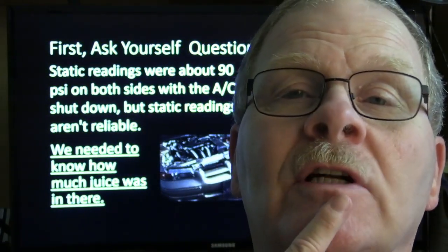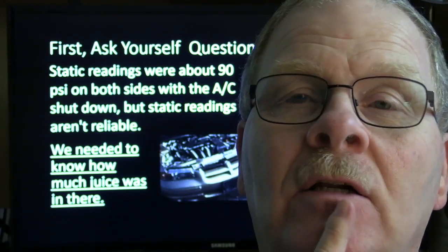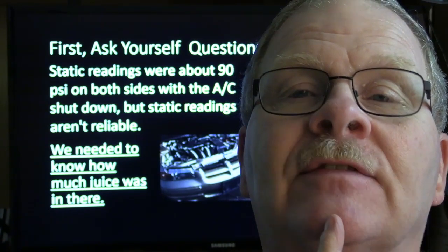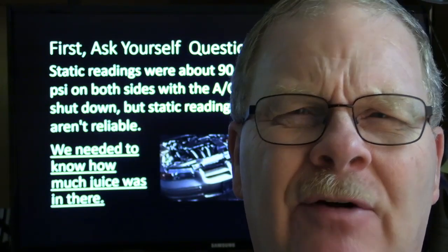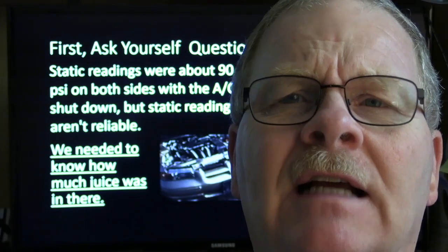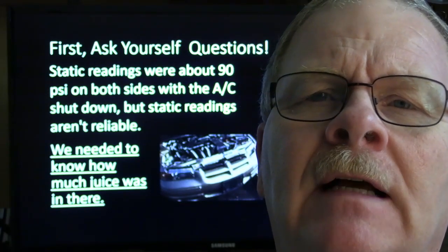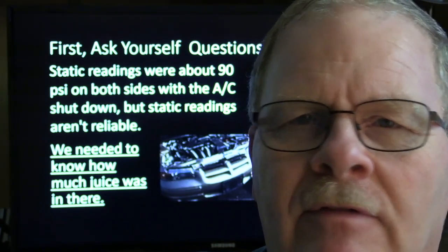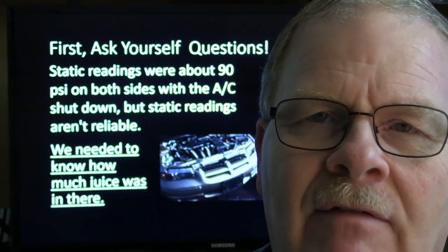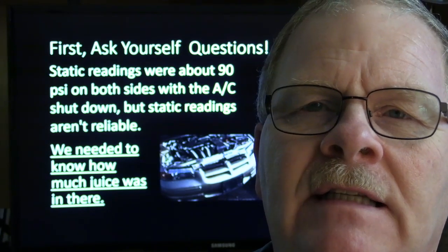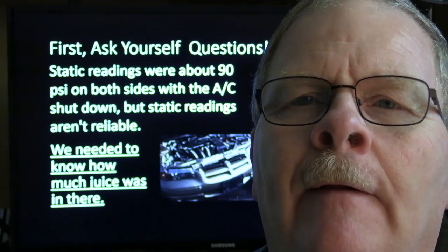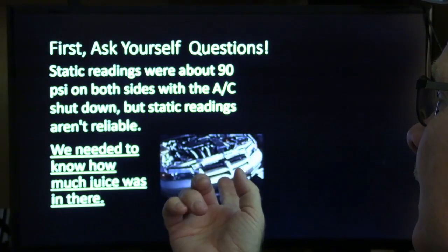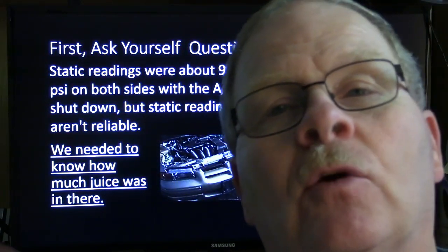Now, venting refrigerant to the atmosphere is highly illegal and will cause you to be fined $32,000 in some places if they catch you doing it. It's basically federally against the law. It's not just California or places like that. But the long and the short of it is, you may not ever have to pay a fine, but don't vent refrigerant to the atmosphere. If you don't have a good way to get it out of there, then just leave it alone and let somebody else work on it. But what we did here, we basically used the machine to evacuate what was in there.